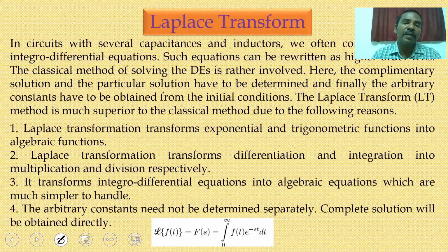While you are coming to the classical method called Laplace transform, it may be a first order system or a second order system. The representation of the equation will be very simple, and once you go for partial fractions, you can calculate the residues in a very simple way. Once you have calculated the residues, by taking the inverse Laplace transform of the overall transfer function, you can get the time domain analysis.